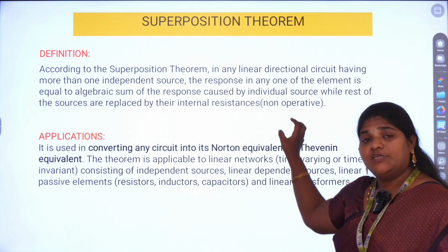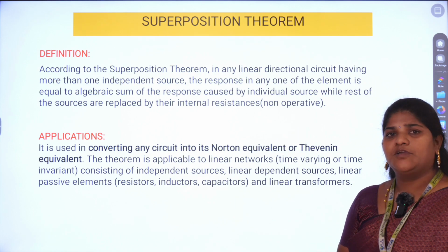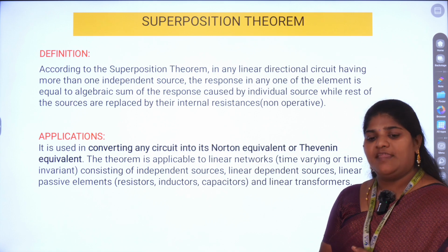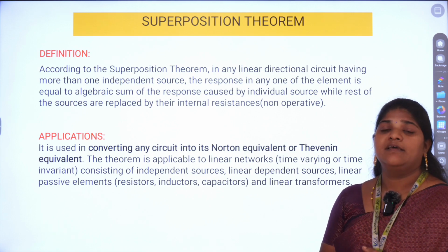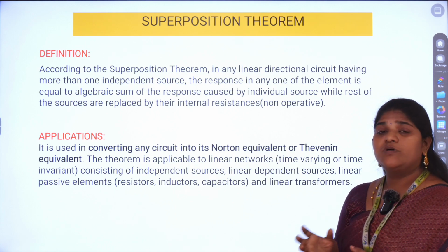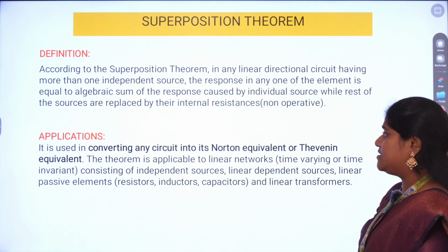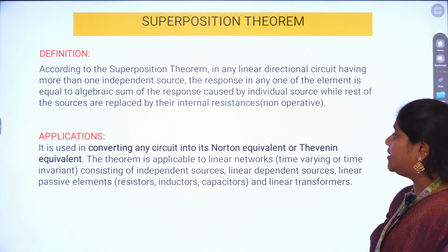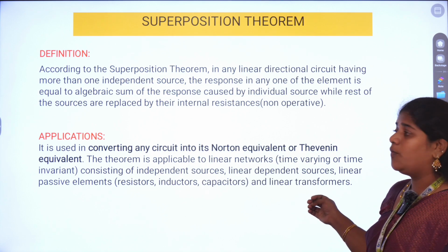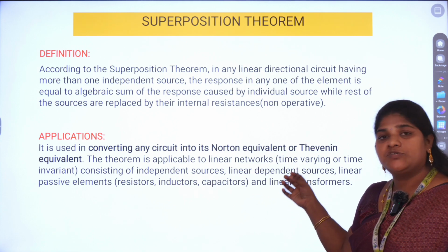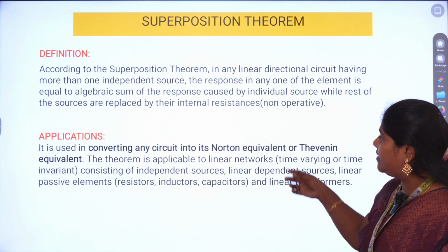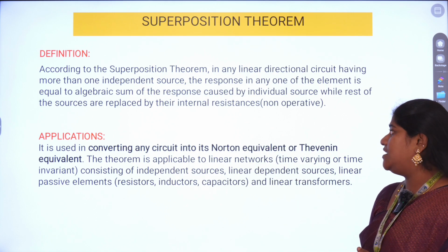The superposition theorem holds good for any circuit having one or more independent sources, and if any response like voltage or current is being asked from any branch or node, then this is the most appropriate technique. It is used in converting any circuit into its Norton equivalent or Thevenin's equivalent circuit.